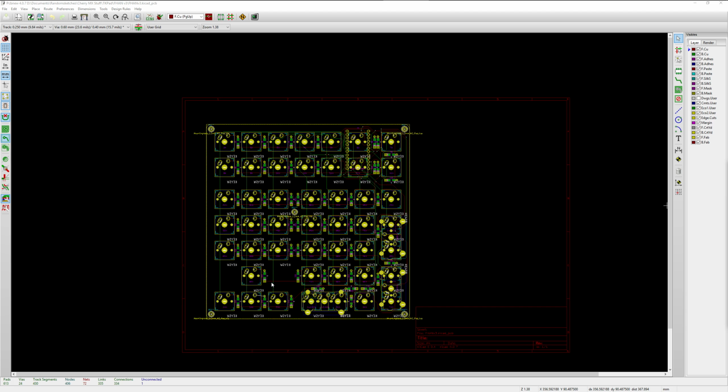And you can see all of these bits and pieces, and then of course if I turn our drawing layers back on that I had taken off, you can see the footprints and so on and so forth. This is when we start using the design rule check tool within KiCad, which is this little ladybug up here, just to make sure that there's no errors. And I have not run this, so if we do get any errors, you're going to see it first and foremost. In a way, I kind of want to see some errors just so that I can run through them on the video, but if there's no errors, then that's fantastic.